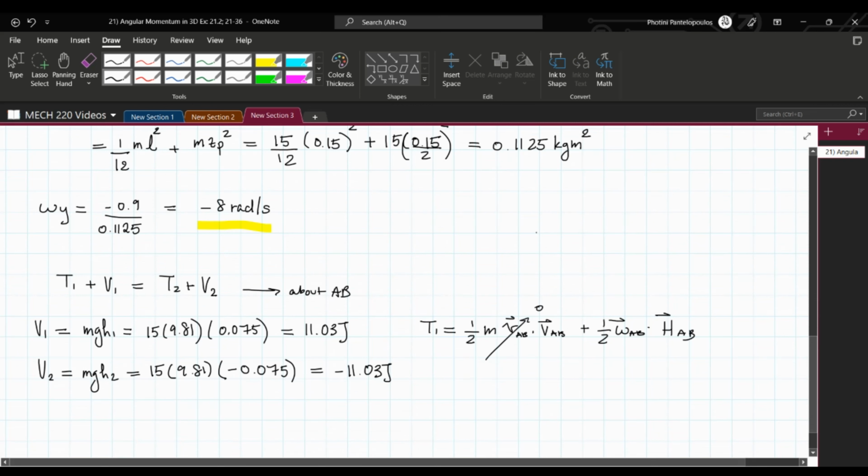I mean, it's the difference between a rotating bar that is rotating about point O and a bar that is rotating about point G. A bar that is rotating about point O will only have kinetic energy that is rotational, whereas a bar that is rotating about G will have kinetic energy that is rotational and kinetic energy that is translational.